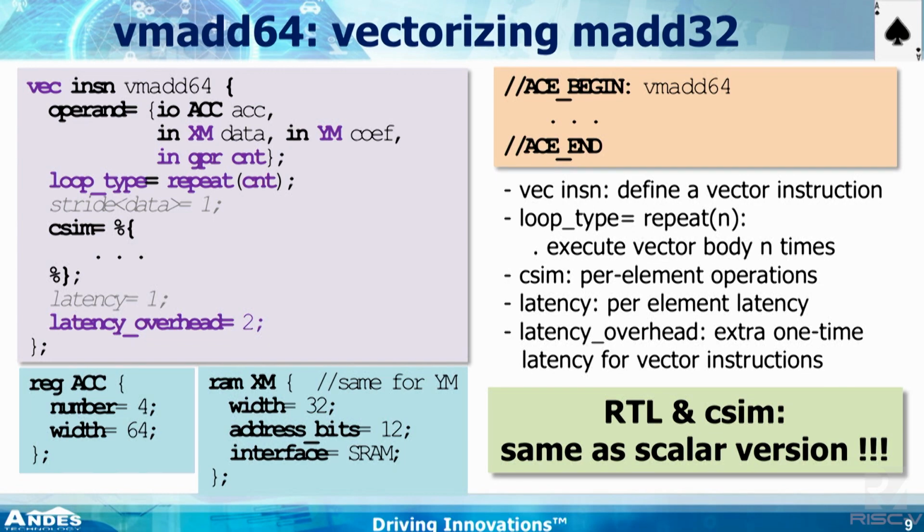With this, you have a vector instruction doing a lot of 16-bit by 16-bit multiplications, accumulated to 64 bits, so you don't lose precision. Now, this instruction would take some time depending on the count, so it would block the main pipeline execution. So maybe you want to put it into the background.